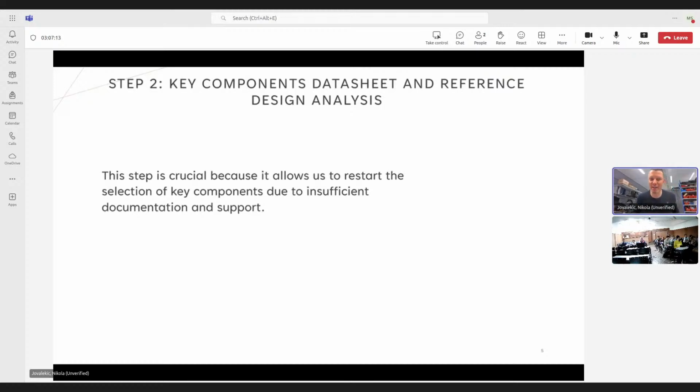I will tell you some tips from practice. What is usually done in industry is that you are not going to design a schematic from scratch for these key components, for example for some processor, microcontroller, FPGA, whatever. There are reference designs already done. Engineers usually use these reference designs and copy them into their designs. They scrap some things they don't need, because these are usually platforms with a lot of peripherals, meant to demonstrate the capabilities of these components. So they put everything in, and you scrap that and just keep the parts you need. But be cautious there, always analyze. Do not do that without thinking.